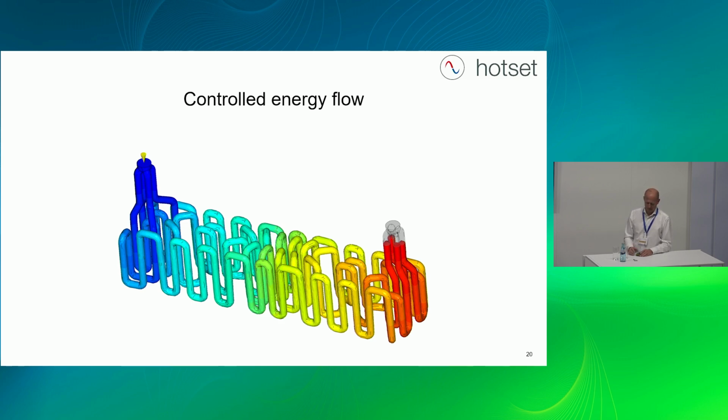And I said, you are disappointed although the technology is working? He said the message, and I said, increase the temperature of the water. But he can't increase anything because in the other machines you get problems. You need to extend the cycle time and everything. And I said, okay, I give you one piece of missing information. You freeze, you shock your part. Stop the circulation of the water during the complete injection process, and just open the valves when you are in the cooling time.